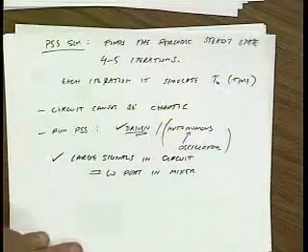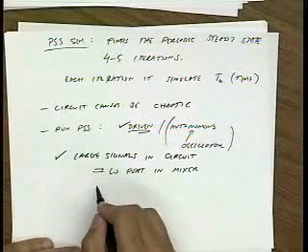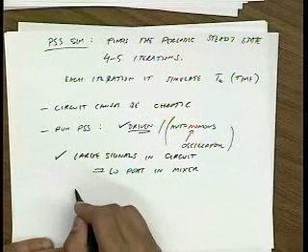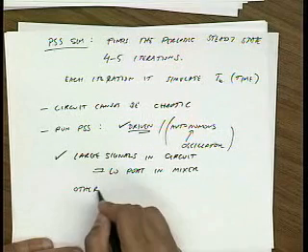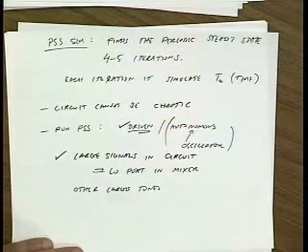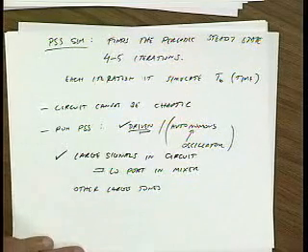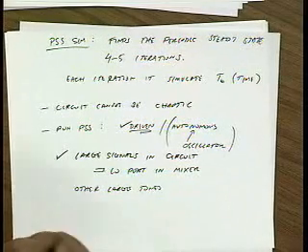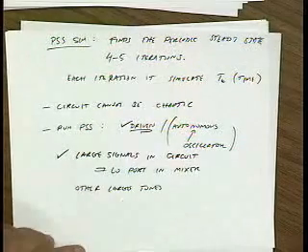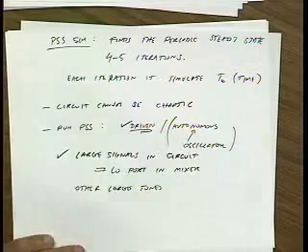There are situations where you want to put in 2 tones or 3 large tones. You could also put in other large tones. For instance, as we'll see, if you want to do a true IM3 simulation in a mixer, you would need to specify at least 2 large tones. Turns out that with small tones you can get away with it, but we'll come back to that.